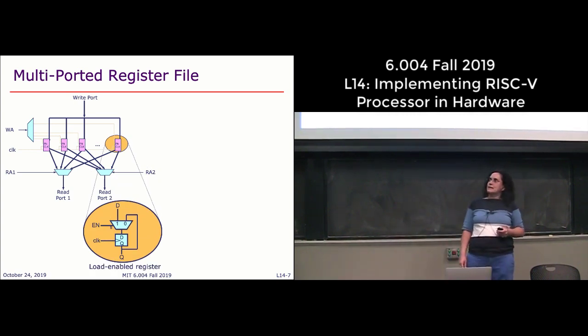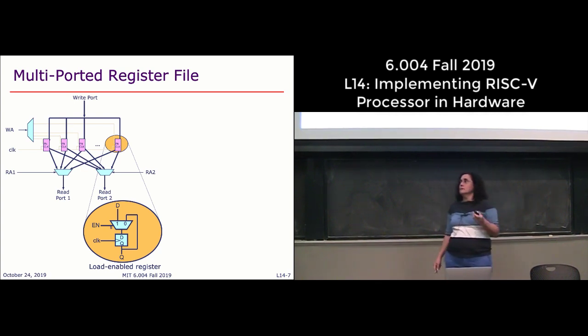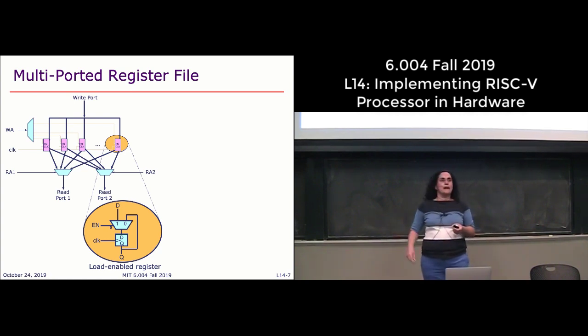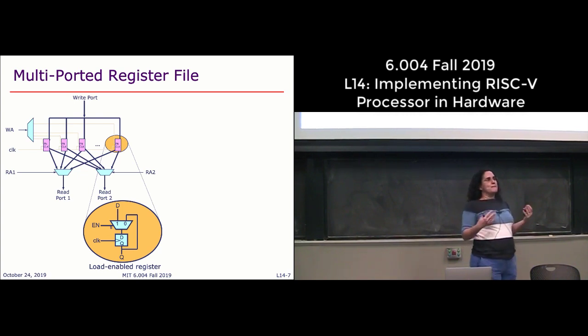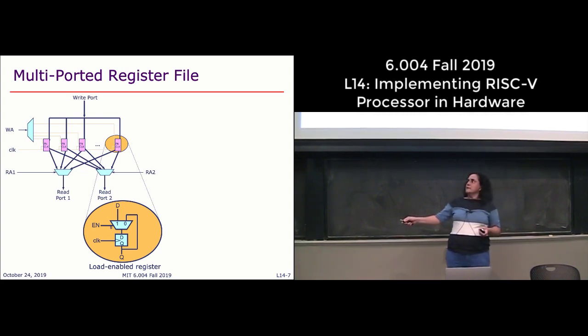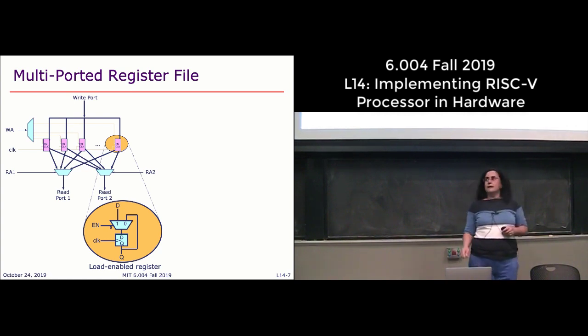So this is basically just a register that's a D flip-flop with an enable. So what does that enable do? Anybody remember? Yep. It tells us whether D should be stored in the flip-flop. Exactly. And that's what this picture here shows us. So we have a flip-flop storing some value, and it's just going to keep storing the same value until the enable is set to 1. Once the enable is set to 1, then on the next rising clock edge, we're going to get a new input, and that's going to now be stored into this register.